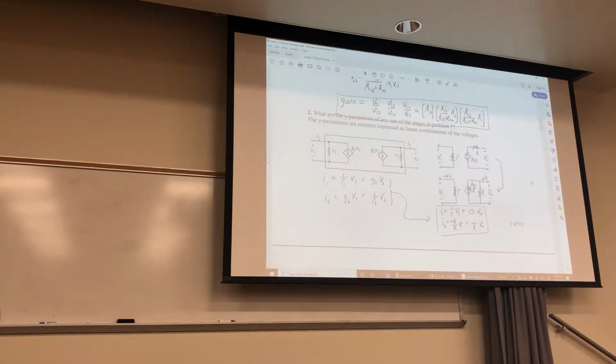Once it's in this form, you can clearly see what the conductance matrix must be. You can clearly see here that G1 must be 0, and so forth. And this right here is your G2 from that. That's because it's going in the opposite direction. This is positive sense going down, and this is positive sense going upwards like that.